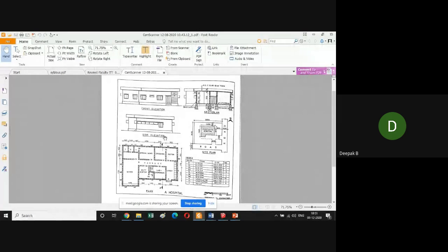You take the lengths from this and then project it sidewards from the front elevation. What you have to do is project it sidewards, take the measurements from the plan. Which dimension? This vertical dimension. E point, we can take that and mark it here. This particular wall will be visible from the outside. So you are drawing the outside view.